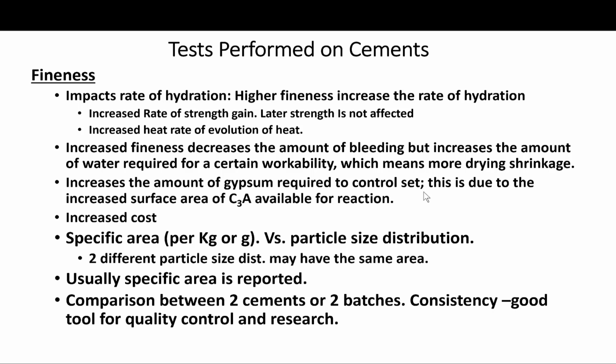Also, the increased cost. If you remember, grinding beyond a certain fineness will become too expensive. And that's actually what we do with the type 3. We grind type 1 finer to declare it type 3, which hydrates faster and gains strength faster, early strength.